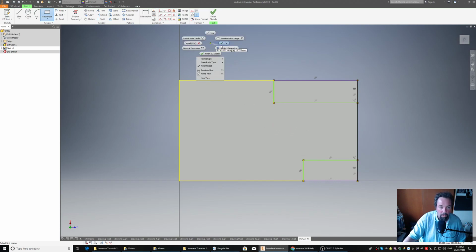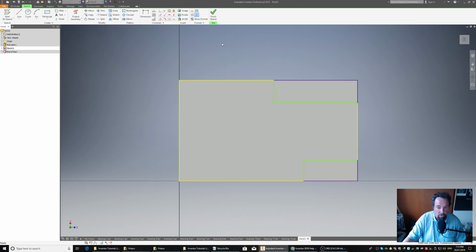And I realize they're not the same, and that's deliberate, so that as I set my sizes using the dimension tool, the size I know I need to have is going to be from here to there. On my drawing says it's 10. Enter. So size from here to there is also 10.